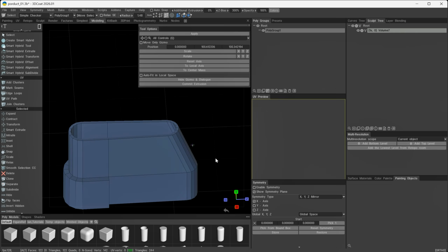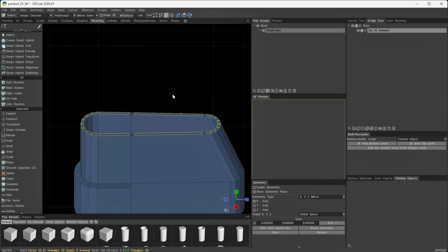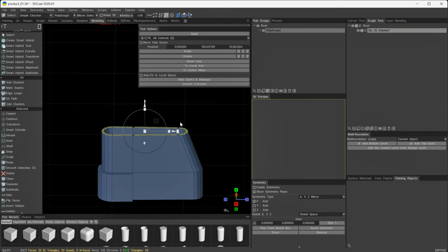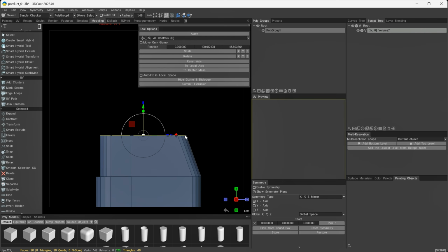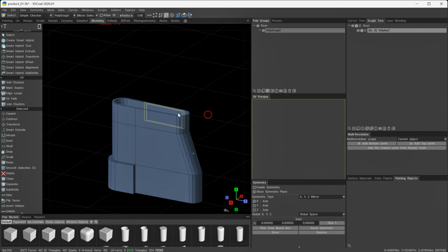Drop the tool. So now I'm going to click on one face here and double click on the next one to select that whole loop. Spacebar, transform, and I'm just going to extrude this up one more time. So let's commit the extrusion and drag that extrusion up just to give us a little bit more height. Escape to drop the tool.